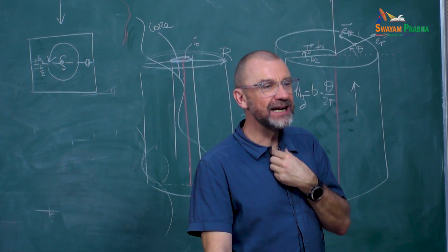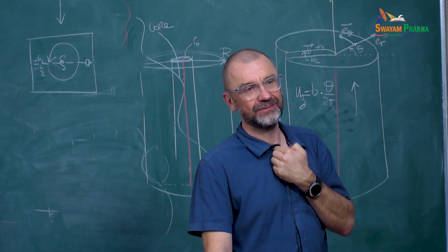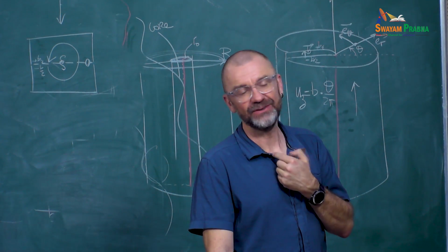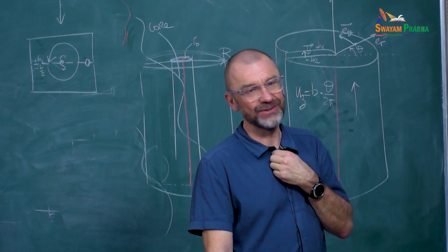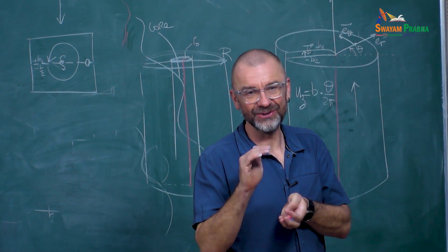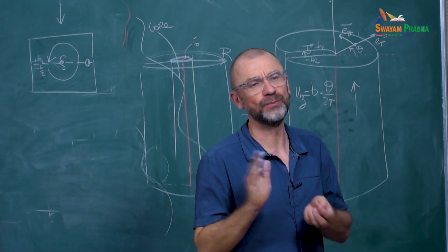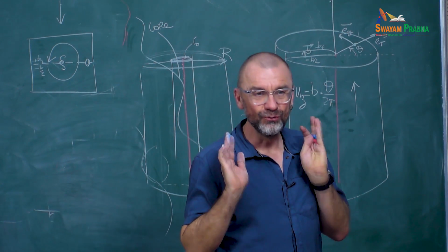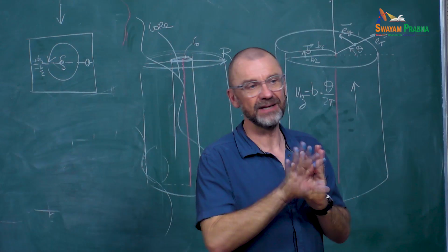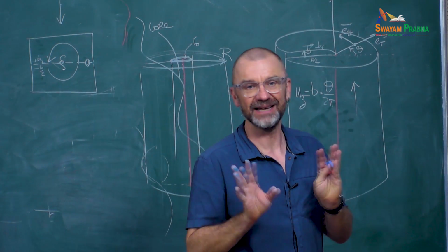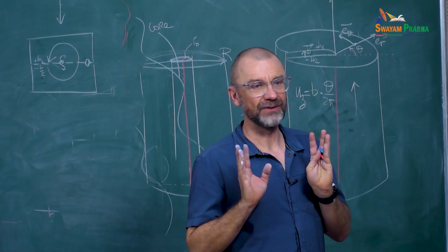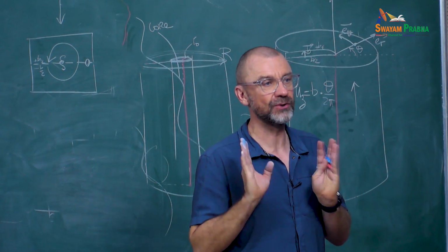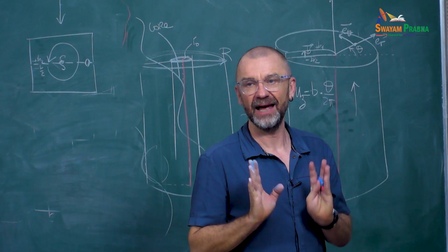If you really want to use periodic boundary conditions, for example if you are doing DFT, with DFT you don't like free surfaces because your simulation cells are so small that if you put a free surface, wow, it's going to explode. So you really want to use periodic boundary conditions because they limit the size effect, as we said earlier. So there's one way to have 3-dimensional periodic boundary conditions.